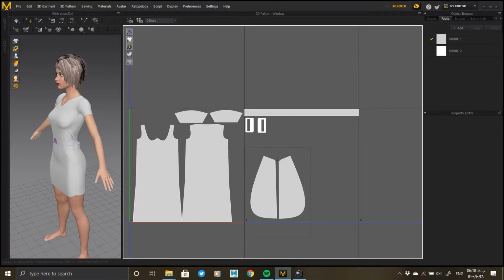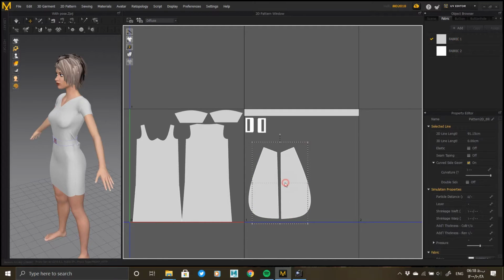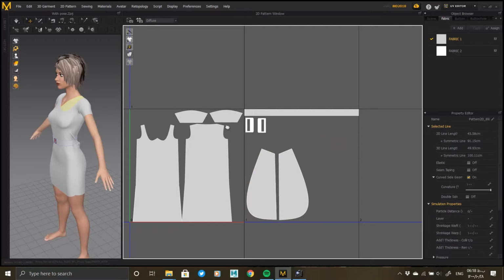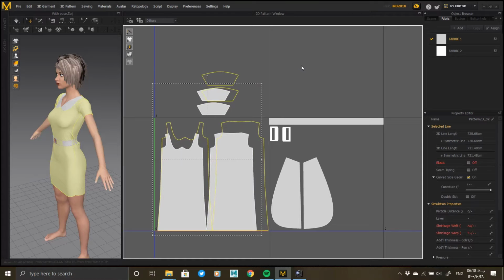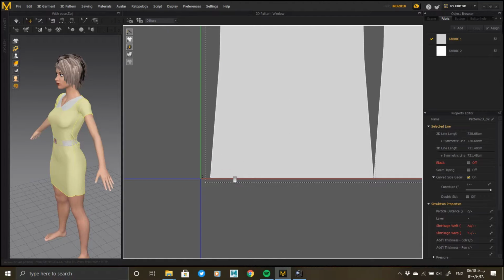In the first case, you can select the model and select the Quadrangulate option, in the 3D Garment section, in the Edit and Context menu. This command allows the irregular topology to become quadrilateral. But in this case, we still see some triangular topologies, and if the model topology is not very important, this tool can be used.